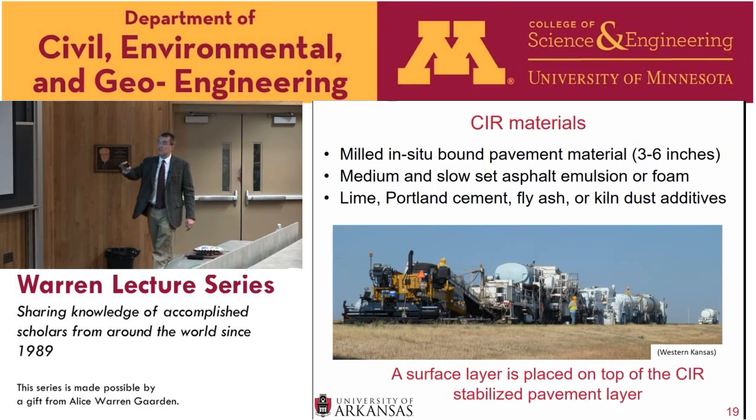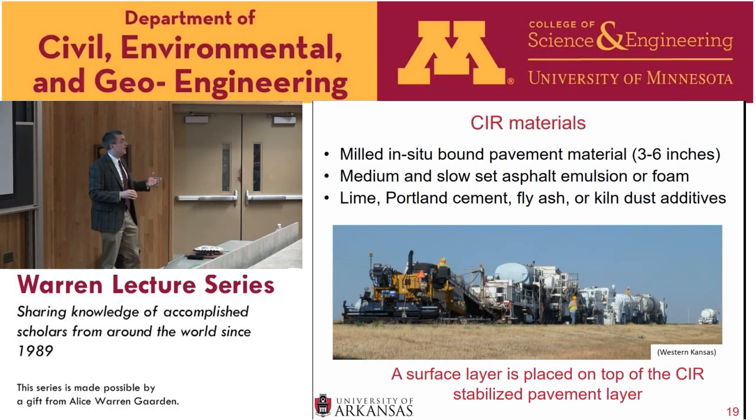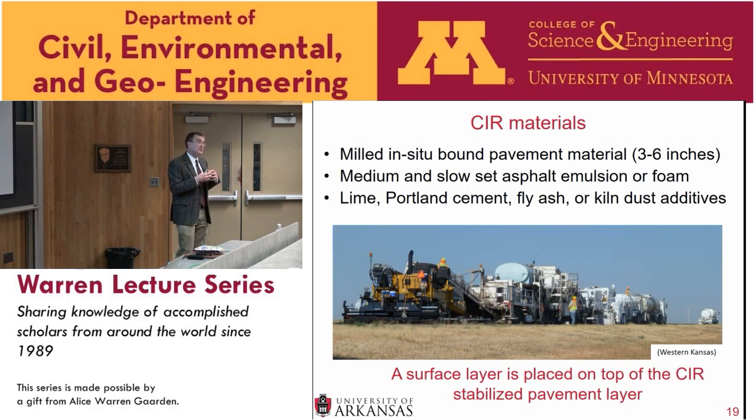Once this new road pops out the back, we call it a semi-stabilized base course. So it's not quite as strong as hot mix asphalt. If you go down into Mihai's lab, he has hundreds of samples of asphalt sitting around there. It's not quite that strong, but it's stronger than completely unbound material, so we call it semi-bound material. It's not appropriate for tires to ride on it, so you put something on top of the CIR. You either put an overlay, a chip seal, a slurry seal, or some sort of surface course so you can drive over this new pavement layer that you have.